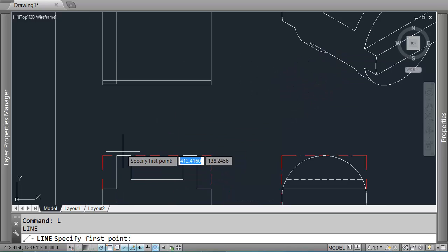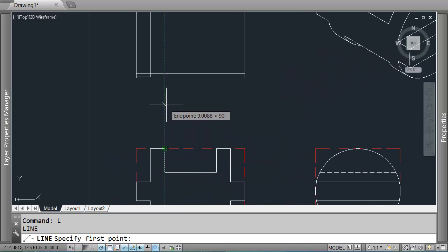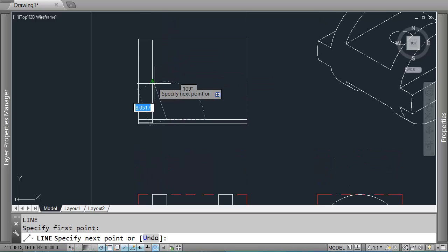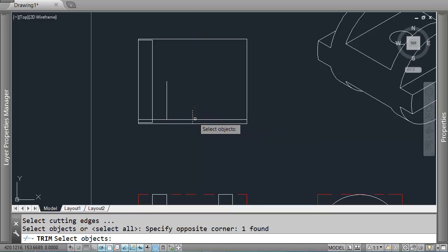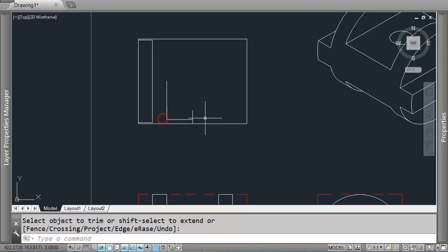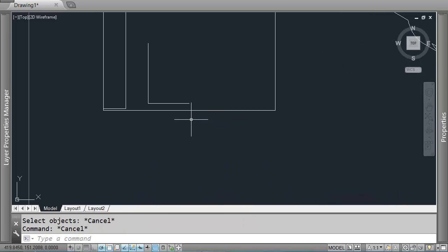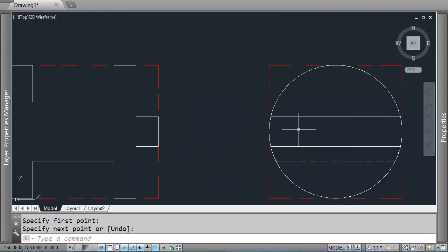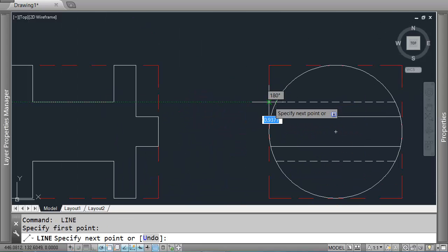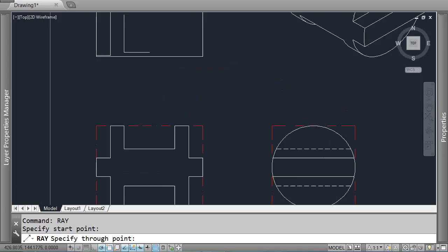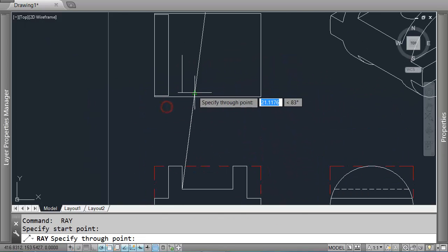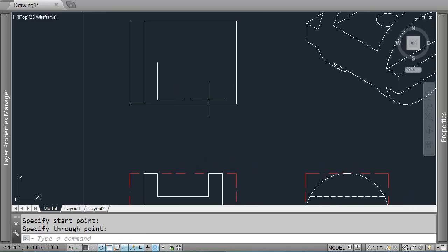The middle rectangle can be located in a similar fashion, so we're going to come up from this point until we intersect there. Go to the middle part of the shape. I'm going to trim off this part, the middle part of the shape here as well. Trim off that. And now I can mirror a couple of times to get the shape in the right location. So from this outer edge, where I located that shape before, that is the distance that we have out of here, which is in alignment with this corner to create that shape. So it's also the edge that we need for this center rectangle.